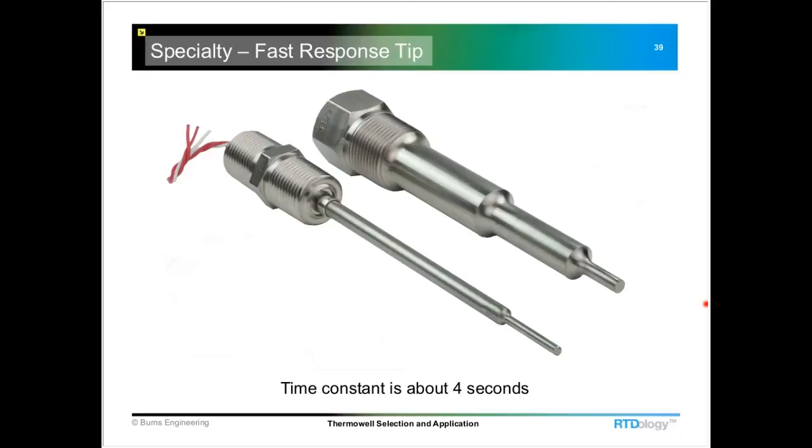One thing that I haven't mentioned yet is the importance of spring loading. This particular sensor happens to be spring loaded. There's a spring inside this threaded fitting. And the purpose for that is to make sure that the temperature probe is bottomed securely in the Thermowell. And it does a couple of things. One is that it keeps the probe from vibrating inside the well if the process has any kind of vibration going on. It also, and it's kind of a minimal help, keeps the tip in contact with the tip of the well, so there's going to be a little better heat transfer right through the tip of the temperature probe.